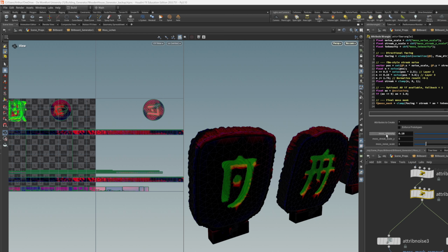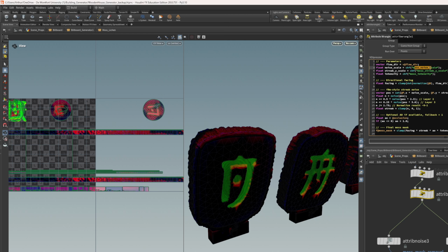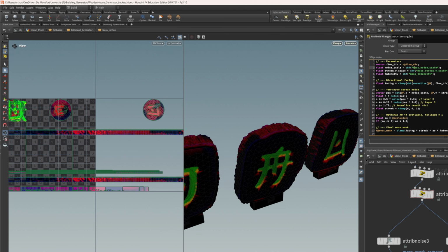And then when you want to reference this, you write CHF because it is a channel float. If it was a channel string, you would write CHS, or CHI for integer. And then you just write the label, and it has to be exactly the same. So if I change this to be a capital M, it's changed the outcome. It's changed the maths because now that's just coming through as 0.